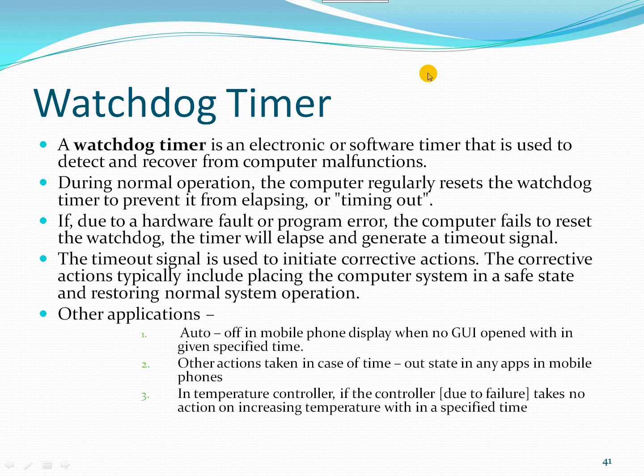During normal operation, the microprocessor will be regularly resetting that particular timer whenever the Watchdog timer reaches the preset count value. So that timer will be reset. Whenever the Watchdog timer is reset, it will think that the particular processor is in the normal state, in a correct and working state.